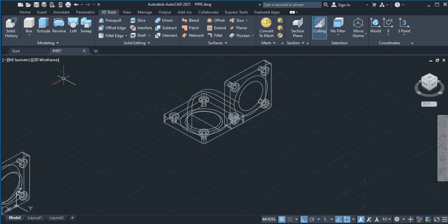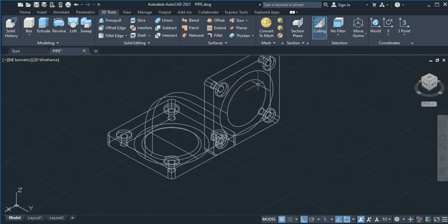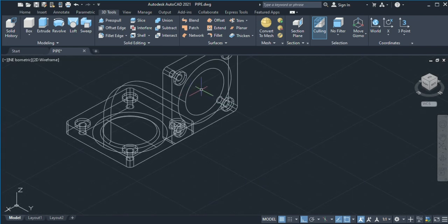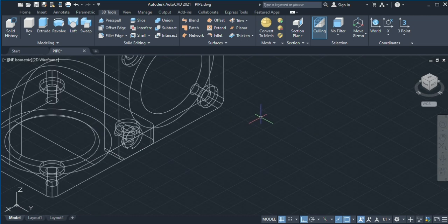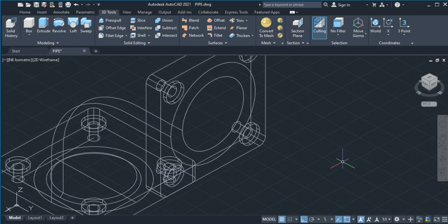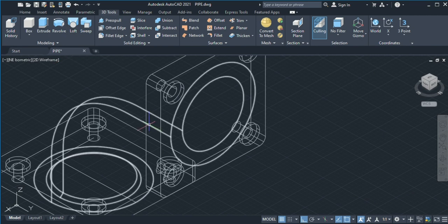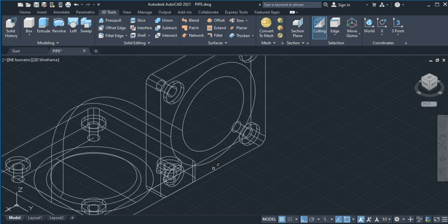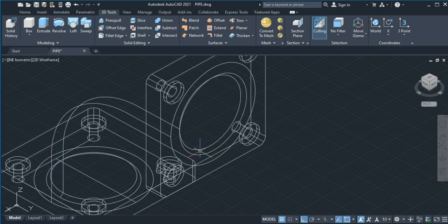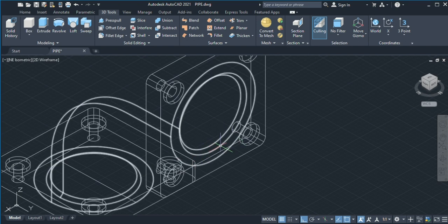So the best way to do this is in a 2D form. For this top one, I have not yet applied the chamfer. I'm just doing it on the bottom pipe, but you can do the chamfer first before we proceed with the subtract command. So chamfer first. We do chamfer on this one, and then distance 10, and then specify surface distance. Select edges, so select this one and then enter. So there, we have already done chamfers of 10, which is what C10 explains.